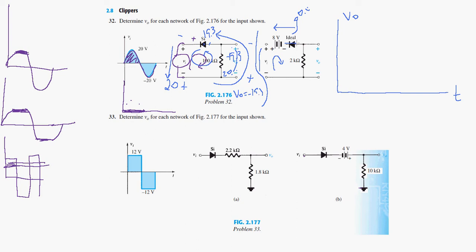So the diode is forward biased, so if we have 0 volts here, and we look at the voltage in this direction on the resistor, anti-clockwise, we'll have 8 volts in this direction, so 8 volts here, 0 volts here, so the voltage here will be minus 8. So we'll be somewhere here at minus 8 when the voltage is 0, for example, the first point here. And so when the voltage here is larger than 0, then we'll start to force a voltage in this direction here.